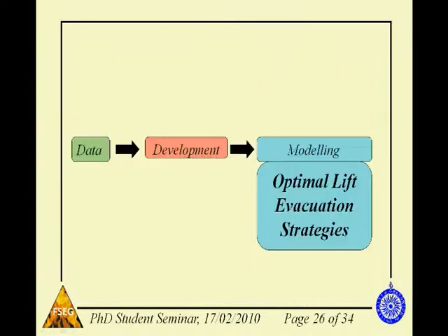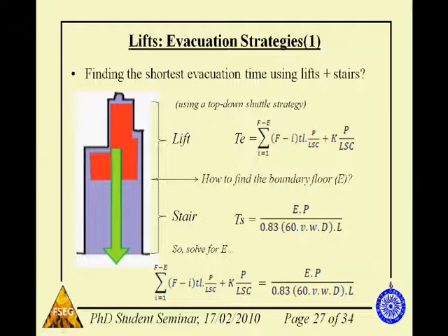So in addition to simulation modelling, we're also interested in finding out optimal lift evacuation strategies and developing some simplistic analytical techniques which could perhaps be used to assist the simulation process in finding our best or fastest evacuation strategy. So one evacuation strategy we're quite interested in is one where the bottom part of the building will use the stairs. Everyone in the bottom part of the building will use the stairs, and everyone in the upper part of the building would use the lift in a top-down manner.